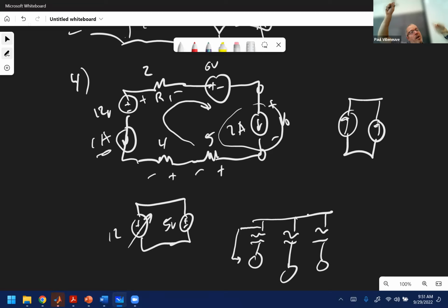So what happens is one has to pick: I'm going to set this voltage and this frequency, because in AC it's frequency. And then all the other generators have to adjust their output. I'm going to pick up the slack, so my voltage will never change. I'll either do something for my speed or something for my power input to make that work. All the other generators have to adjust themselves based on what that call is. And so that's what's happening at the grid level.